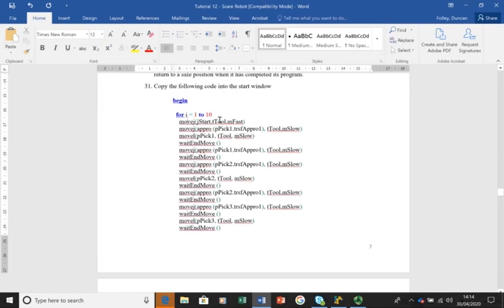It's going to have a gripper at the end called T tool, and it's going to move at a certain speed, and we're going to take the default settings for a variable called M faster. It's like M fast and M slow. You can create your own speeds and feeds, but for us it doesn't really matter. And then it's going to move to a point called pick 1, which we will teach it. But we don't want it to move straight to the first position where the box is, to pick up a little box.